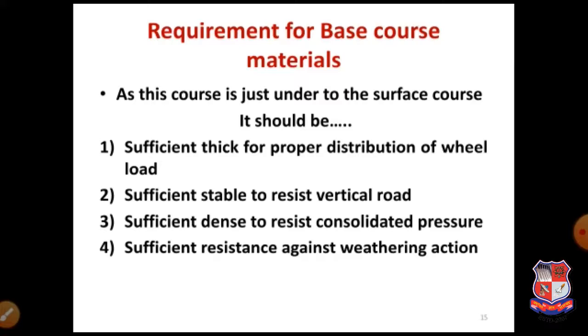The requirements for base course materials: as this course is just under the surface course, it should be sufficiently thick for proper distribution of wheel load, sufficiently stable to resist vertical load, sufficiently dense to resist consolidation pressure, and have sufficient resistance against weathering action.